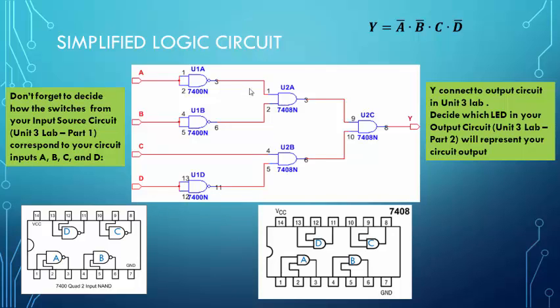And then after the AND gate over here, you should get A' and B'. After this AND gate over here, you should get C and D'. And then you put another two-input AND gate that will AND this group and this group together. So that's why finally you will get those four variables ANDed together.